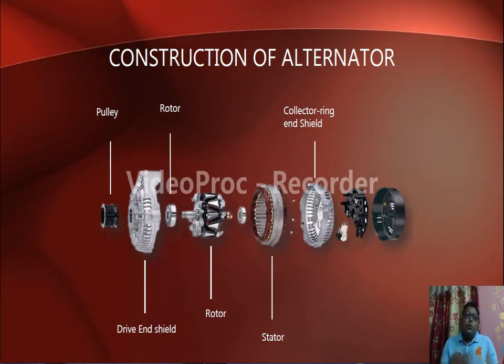Now over the rotor, generally we place armature conductors. These armature conductors cut the flux and generate the EMF, and that EMF we are going to use. So if we think of a large alternator, the weight of the armature conductors is very high. If we want to rotate this huge weight machine, it itself needs a very huge power.